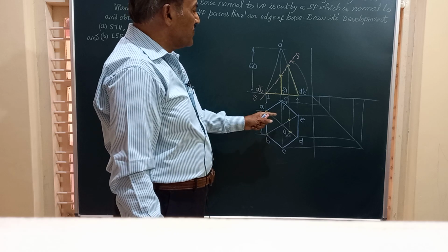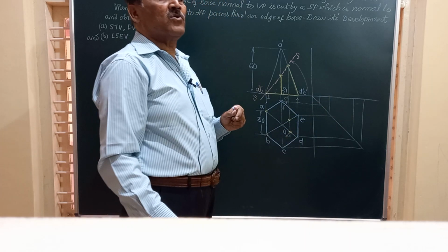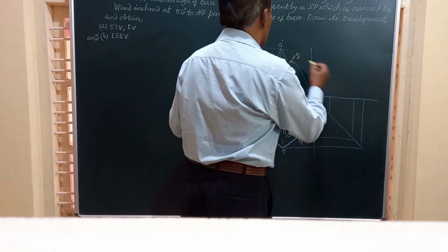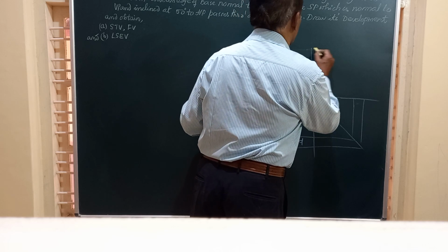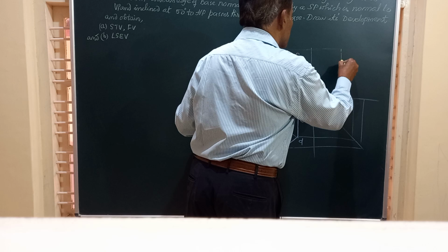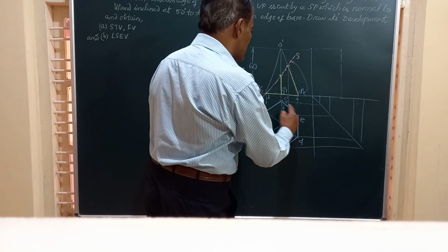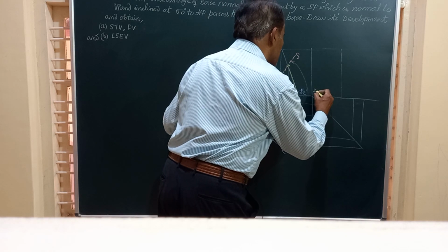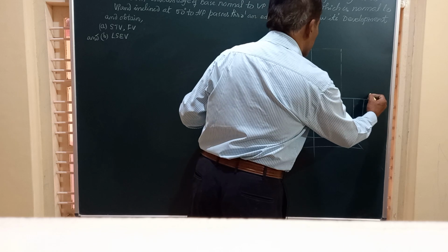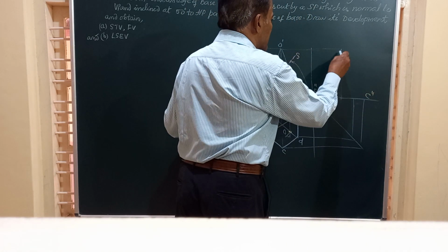Hence, to obtain that, friends, let us draw the left hand view of the pyramid by looking in this direction for the given height of 60 mm. So I draw a horizontal line, mark the center of this, and transfer all these points to that. That is, you got F first, that is F double dash in the end view, last is C double dash, and we have to join them by straight lines.